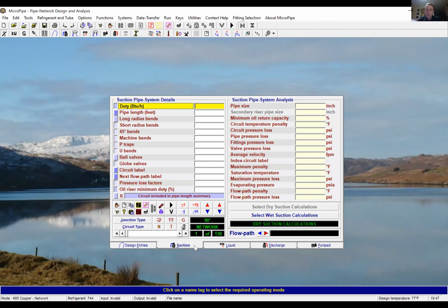Damon, there isn't really one. From my perspective, I'm going to start talking here in SI units, and apologies. Anybody from the UK will probably follow the British Refrigeration Association guidelines, which state the intended maximum velocity in a horizontal suction line be 10 meters per second, and in a vertical, 15 meters per second. I'm not too precious about those through experience.